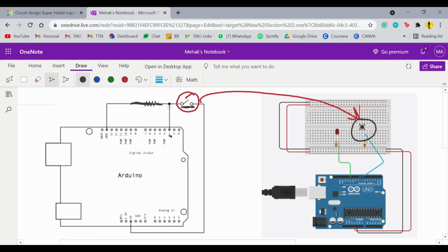So what is going to happen? This pin 2, and in our case, we have pin 7. So what is going to happen is this will become a circuit on its own, and this will be a complete circuit. Current will flow through it. So this pin will become high. 2 will become a high pin, which is 7 in our case. 7 will become high, and the LED will turn on. That means whether or not the button is pushed, that will not matter. The LED will remain on. Now, imagine that the resistor is still not there, but we push the button, so the circuit is complete.